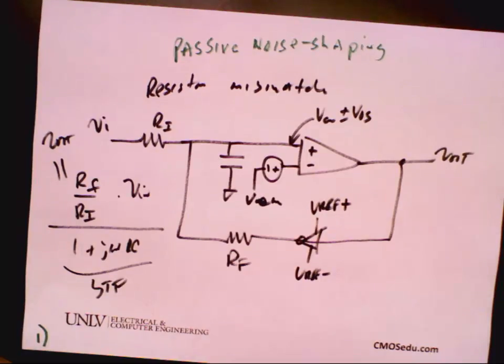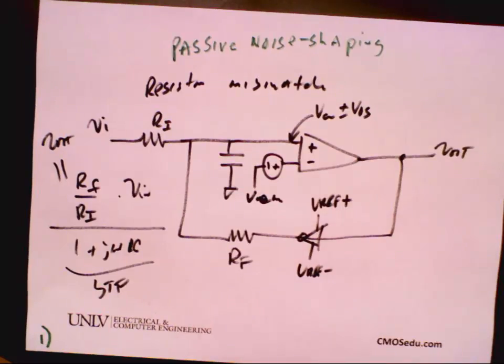Okay, what about the offset? What do you think is going to happen with offset? Well, think about it for a sec. Well, it changes the switching voltage, but what am I going to see in my output? Well, it's going to linearly change with the offset, and I want to show you that. All it's going to do is add or subtract to your signal, okay?